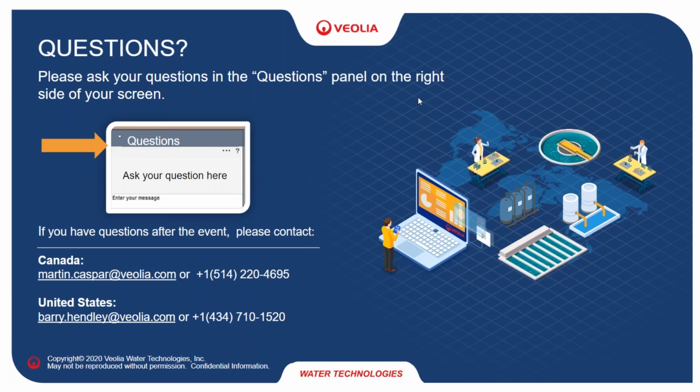Another question confirming that they should sample sand at the discharge of the hydrocyclone. No, grabbing it at the underflow is one of those. If you remember the calculation, there were two sand calculations in each of the boxes that I had. One is for the underflow, and you multiply the time that you had grabbed it, and that number for the underflow is going to be a different flow rate that you calculate.